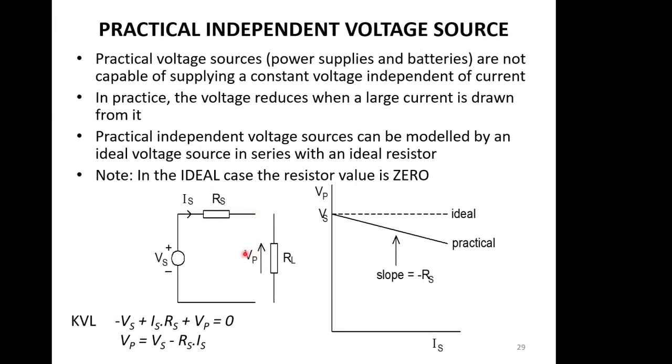A useful case to understand is that when this resistance is equal to this internal resistance, the current flowing through here, well, the voltage that you get across these 2 points will be half the open circuit voltage. That's a really interesting point, but we'll look at that going forward. So effectively what we've now got is Ohm's law applying here, and we've got the equation of a straight line defining our voltage source.